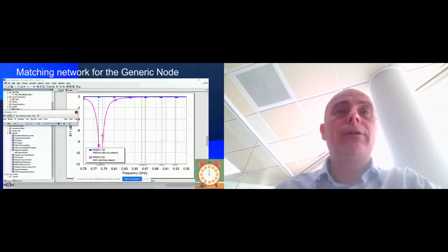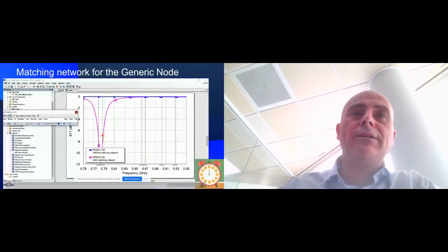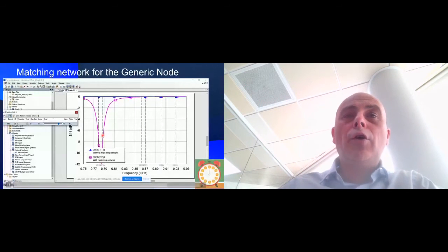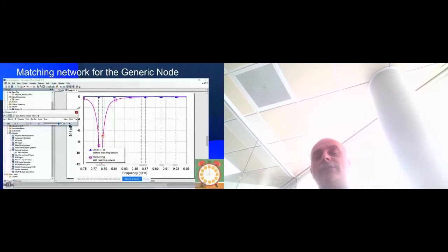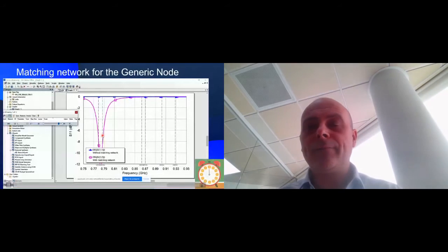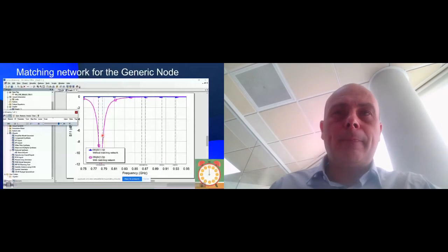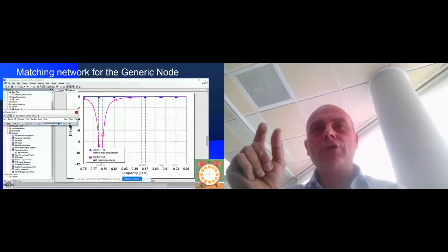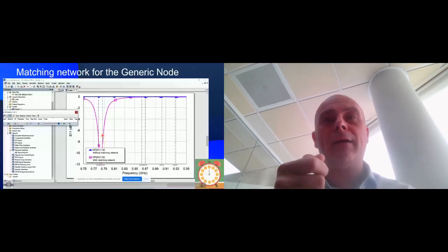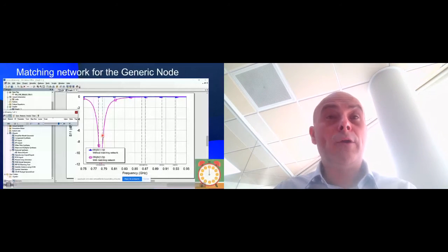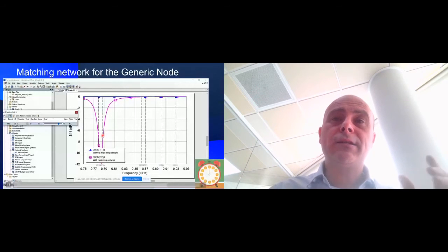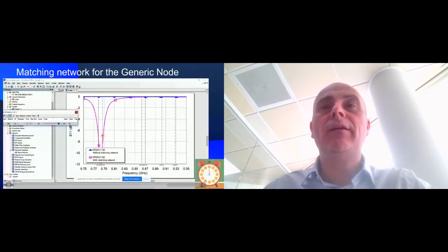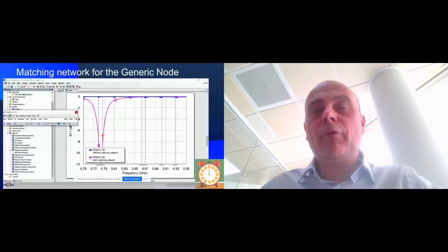And also, by tuning, by decreasing the inductance of this value, you can now also operate, for instance, in LoRa in European bands. Even more attractive. Imagine you have this matching network with your fully populated PCB, and once you put the plastic cover, you detect some detuning. Well, it's simple. Then you can retune the antenna when you are close to mass production, if needed, by just tuning the matching network and just shift the response to be within your frequency response.